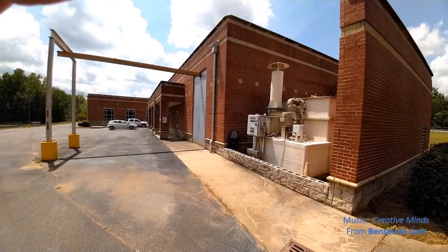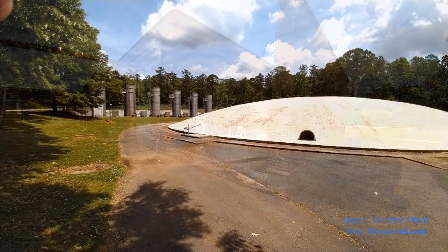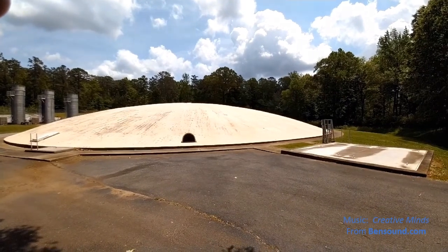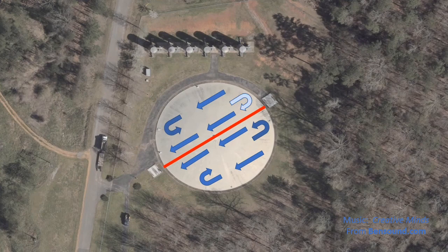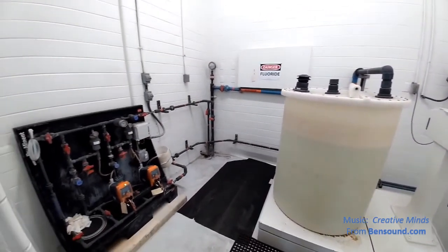In the case of an accidental gas release, a scrubber will pull chlorine from the room and deactivate it. Now, back to the chlorine contact basin. The chlorinated solution is injected prior to the basin, and the water meanders back and forth between baffle walls, so the water has plenty of contact with chlorine before leaving the plant. The basin also acts as a storage tank. The water is then fluoridated for dental health.